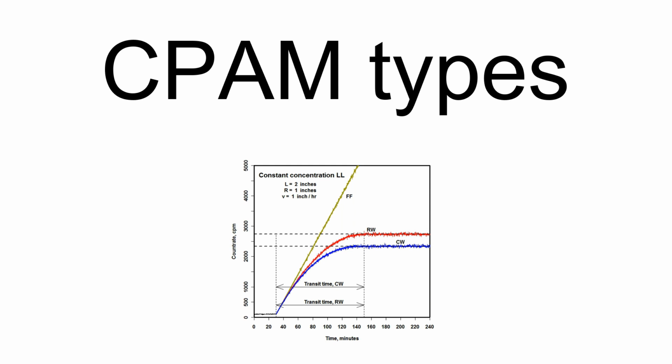As the air passes through the collection medium, usually a form of filter paper, particulate matter is deposited onto the filter in either a rectangular or circular pattern, depending on the instrument's design, and then the air continues on its way out of the monitor. The entire deposition area, regardless of its geometric shape, is assumed to be viewed by a radiation detector of a type appropriate for the nuclide in question.